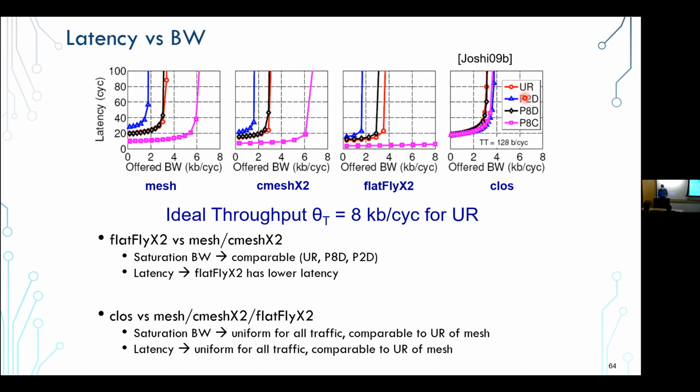If you go to other patterns, which are very localized point to point across, that are more than the average of the mesh, you end up with very bad mesh latency, and actually very bad throughput, because you're communicating in pairs across a large section. You're traversing many routers, a lot of collisions, and your overall throughput basically suffers.